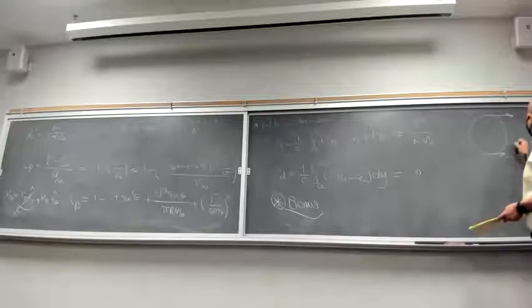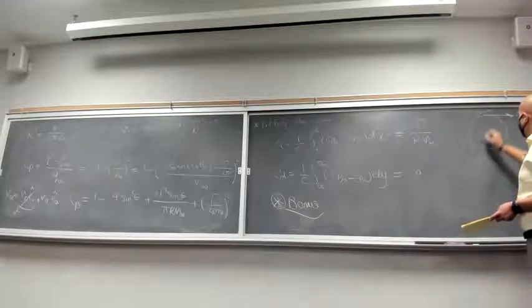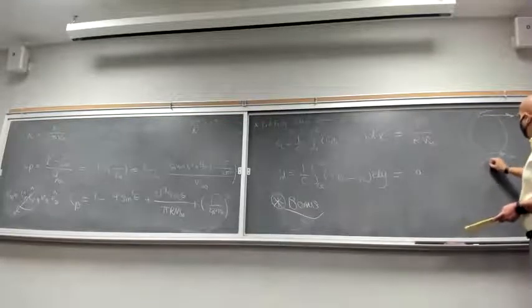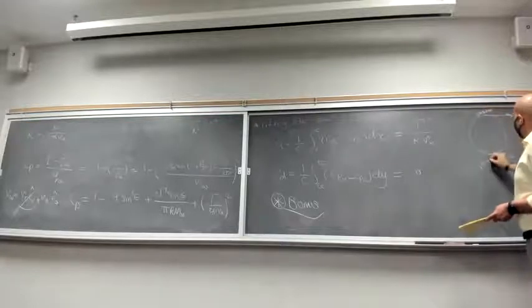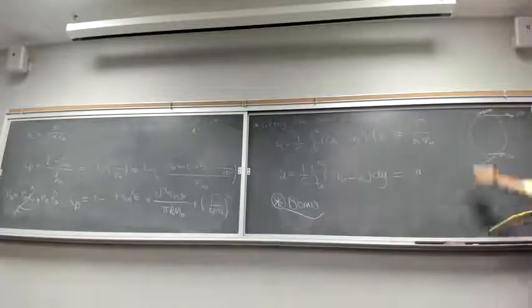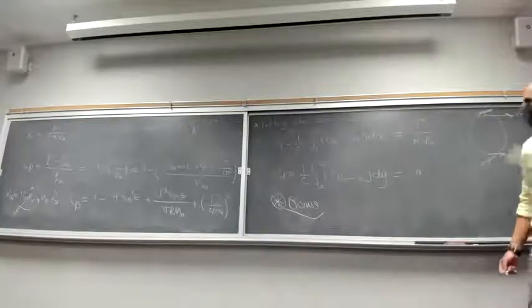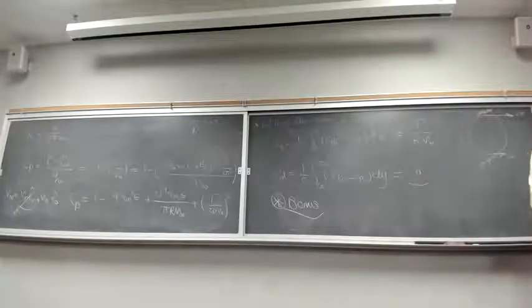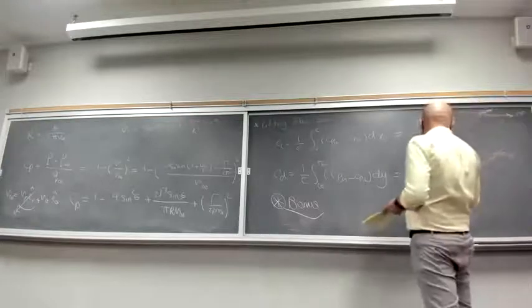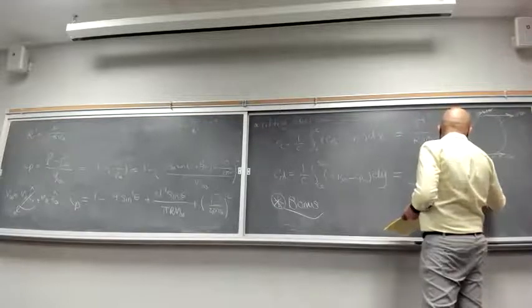because of the pressure difference on top and the bottom, you're going to get lower pressure on top and higher pressure on the bottom. You are going to lift up. But the drag is again going to be 0, which we said is called the D'Alembert paradox.